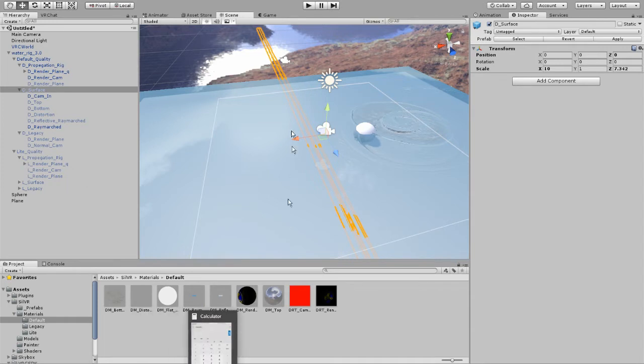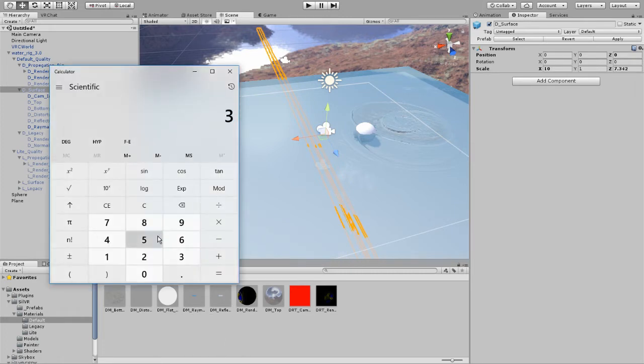So first off, let's start with the first step, and see how many pixels we want per meter. What I typically do is around 192, but this is a larger one, so I'm going to tune it down to 144. That means for each one of these units, I'm going to have 144 pixels along that axis. Now be careful with this, because the resolution makes a huge impact on performance, so don't make it too crazy.